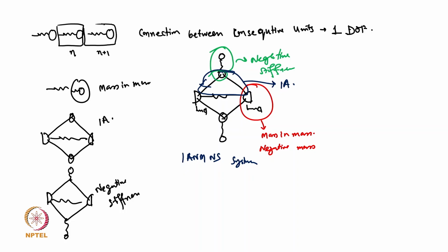So that combines all three different forms of the general units of the metamaterial. So it's called a generalized monocouple system. And if we are able to solve that generalized monocouple system, we can get all the properties. So let's see how we can solve it. Let's first take the basic unit cell of a generalized monocouple system.